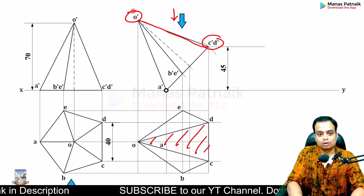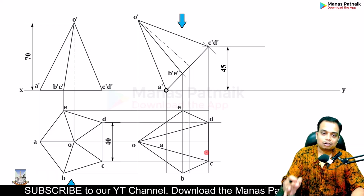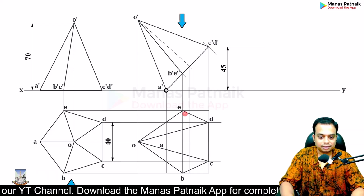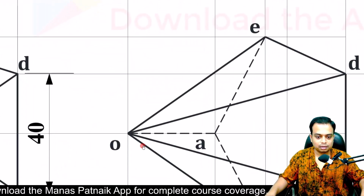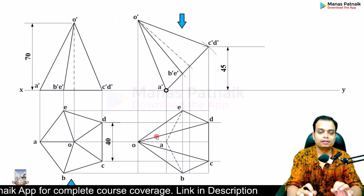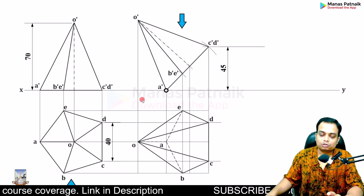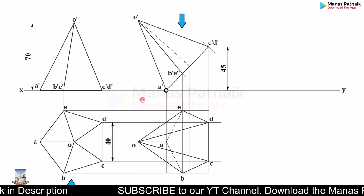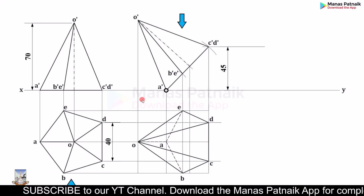Okay, O, C, D, and O, C dash, D dash, these 2 triangles are also visible. What is not visible is a hidden feature which can be represented using dashed lines like this: A and E, A and B, and then A and O. Let me zoom in. Okay, this also is a dashed line, right? Don't worry, I'm going to make the construction stuff much lighter in the final slide. Make sure that you are drawing all of these projector lines very, very light, 3H or 4H pencil preferably. Okay, sir. Now that is done. How do we proceed now? So where are we? Let me switch on the camera again.